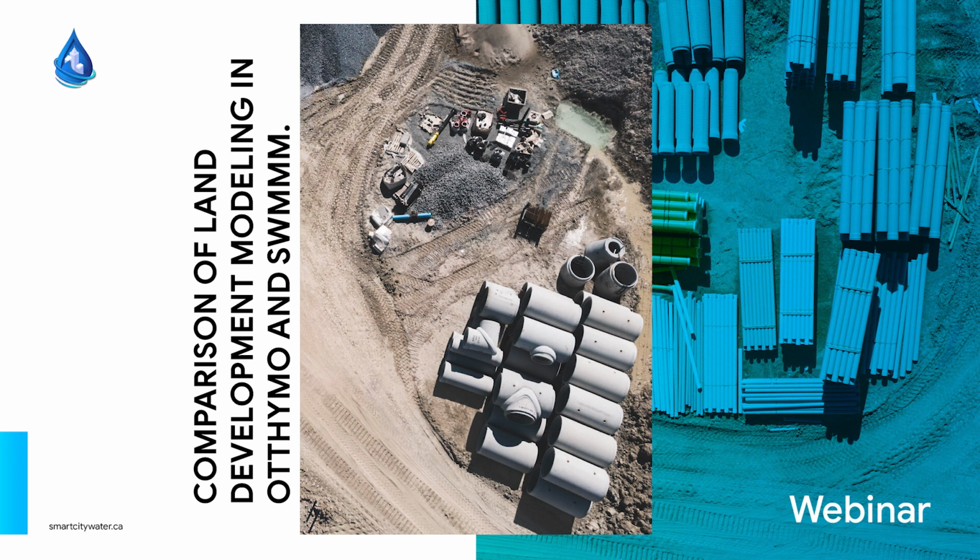I think you're asking about the question from 2 weeks ago, for the webinar, and I think we mentioned that the pond design tool will be released this month. Right now, what people can do is put in a rating curve, depending on which software you use. If you use OTTHYMO, you can give the rating curve, which is basically the discharge in relationship with the volume. So that's a rating curve.